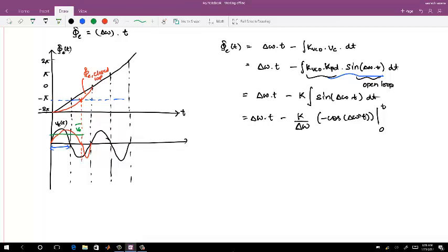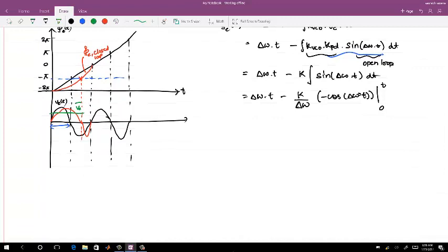The thing is, whether the PLL locks to that period is a question. It may lock, it may not lock, and that actually defines the different kinds of ranges for the PLL. Whether it will always lock between 0 to 2 pi is not at all necessary. The assumption I am taking is that the delta omega I am considering for the sinusoidal thing is fixed for that period. For that period, this will happen.